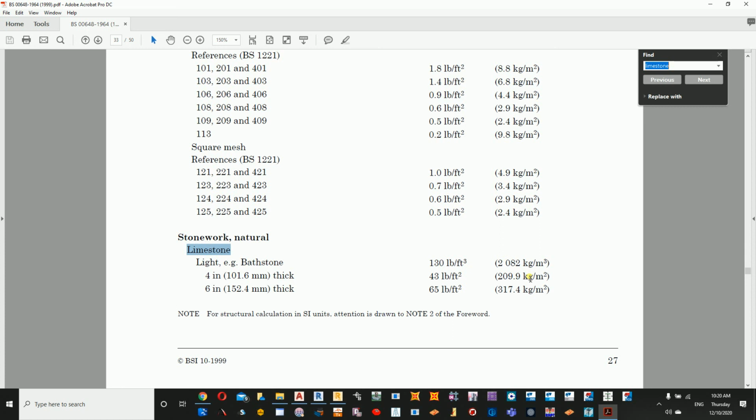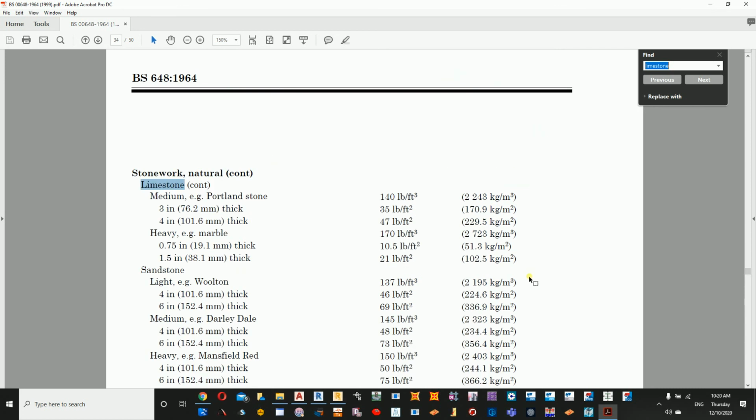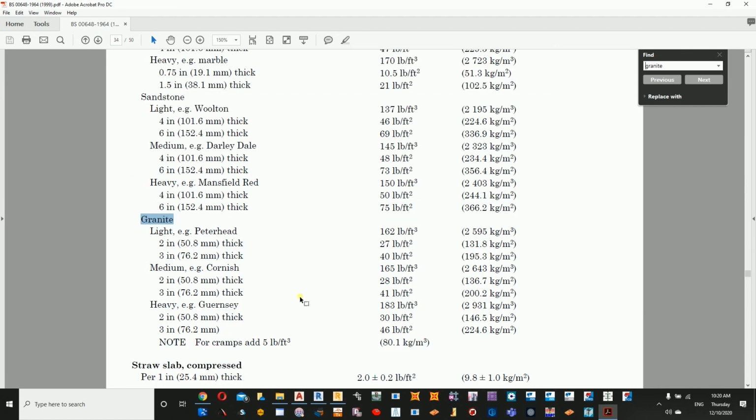I don't want to say a value for you, and I'll give you that sample. We used to use it, but once again, that varies. For example, somebody who's using granite, let us check granite. It depends if it's 50 mm thick or 75 mm thick, the weight will vary. Here the loading is 130 kg per meter square. Here it's around 200, because of the 25 mm difference between them.